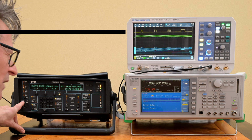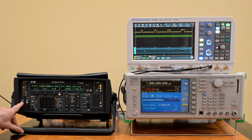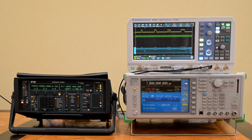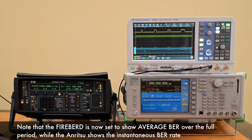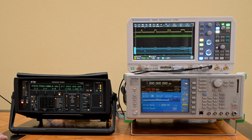If I insert some single errors, I see 1 times 10 to the minus 6, and now it disappears again. So these are single errors. And once I go to a continuous error insert, I get 1 times 10 to the minus 3 errors, so 1 error out of every 1000 bits. And that is the same error rate that I got on measuring the device by itself. I should restart it here again to make sure I get the same averages. But it basically means all is fine, and it's sending the rate that can actually be measured by the Anritsu in the same way as one would expect.